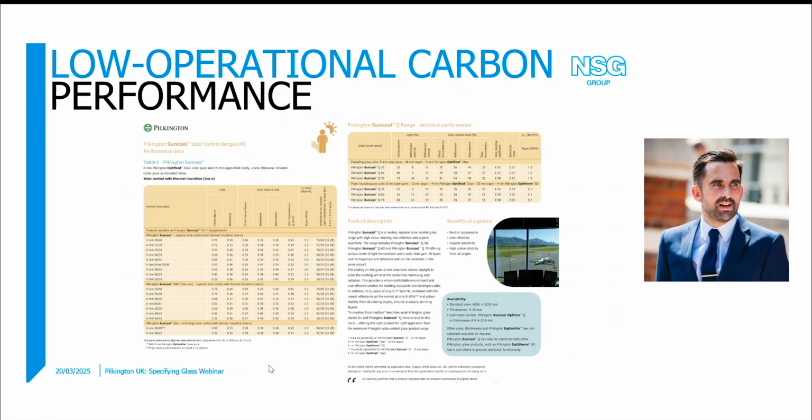So for optimum performance in commercial buildings, solar controlled glass is used. Pilkington have a product called SunCool, a collection of coatings which are recommended. Key to choosing the correct solar control glass is understanding what your project target G value is. Once this is known, that's almost the anchoring point. Once this is known, we can review the most suitable coating and then understand its appearance.